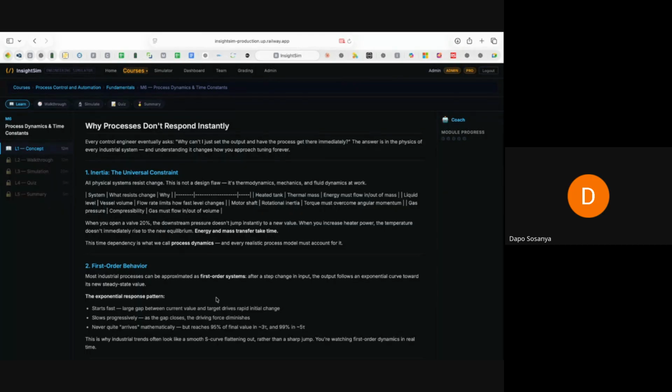The explanation you gave about the scan time is perfectly spot on. The time it takes to read the input, execute the program, update the output, run diagnostics, and then start again. So it's a time T, right, in seconds. So how critical, what is the importance of that scan time when I'm writing my program? I'm not going to tell you. I'm going to give you as an assignment. If you don't tell me.